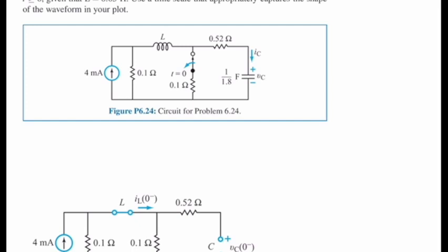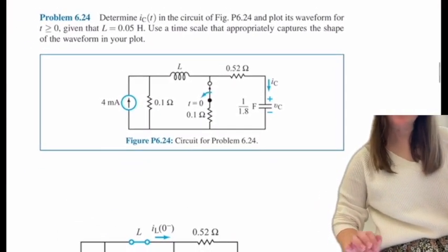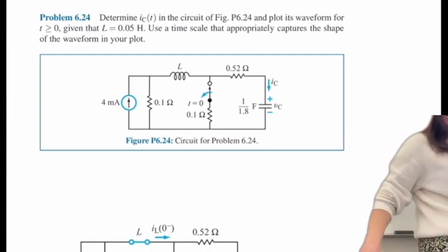Okay, and then we're only looking at the relationship between the inductor and the capacitor. Right, like the middle line. But they're on the same frame. If the current source becomes a wire... The current source doesn't become a wire. The current source becomes an open circuit, and you suppress the current. So sorry about that. L is 0.05 Henry. You are going to need that.